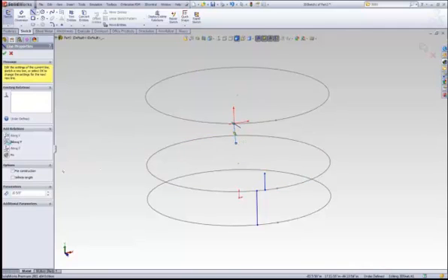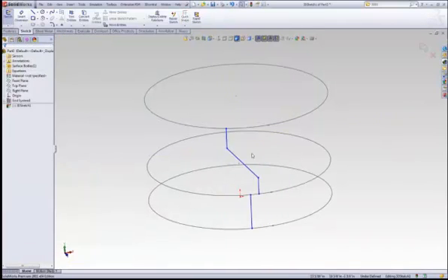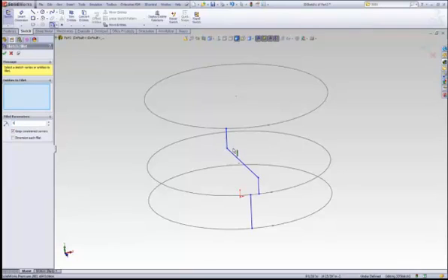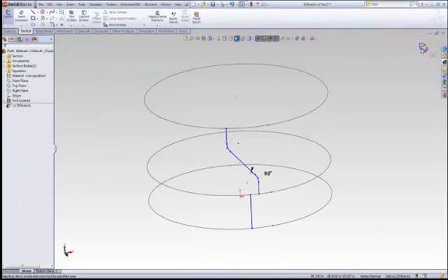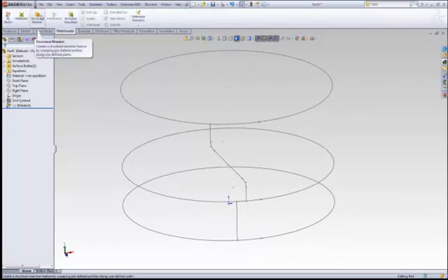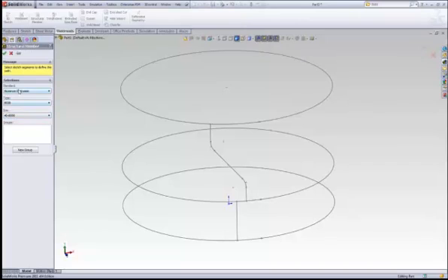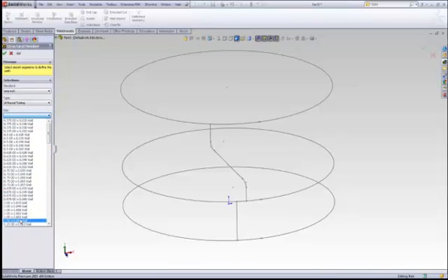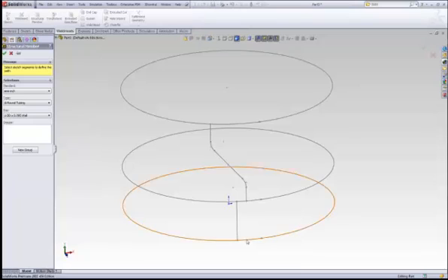Oops, wrong way. And we'll add maybe a 6-inch fillet there and there. Okay, good enough. So there's our profiles that we want to use. Again, we'll go to structural member in weldments, and I want to use round tubing here. Choose our size. Any size will be fine.